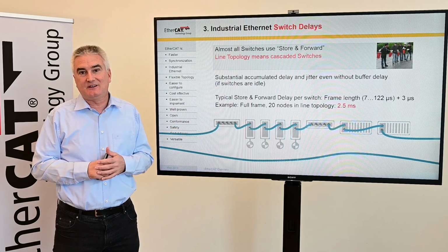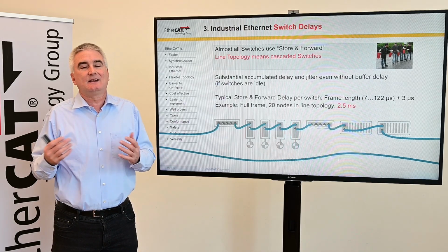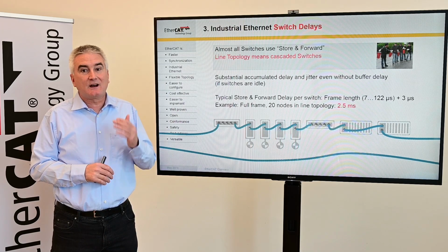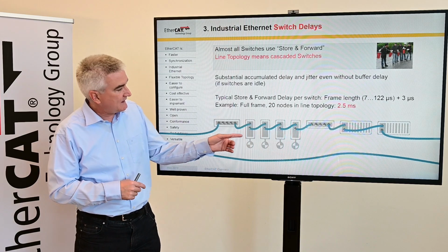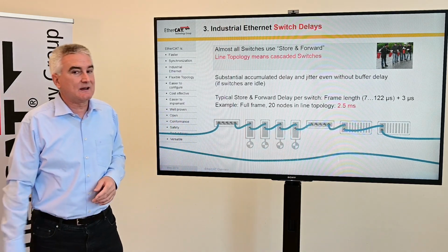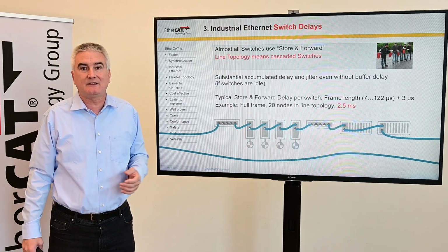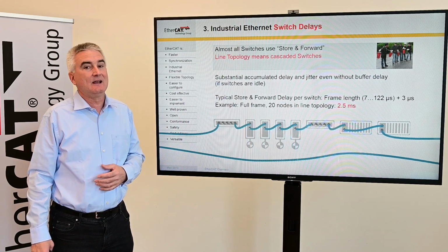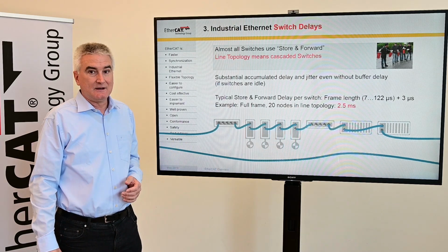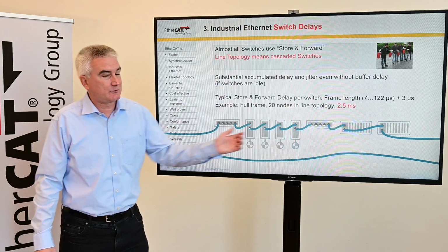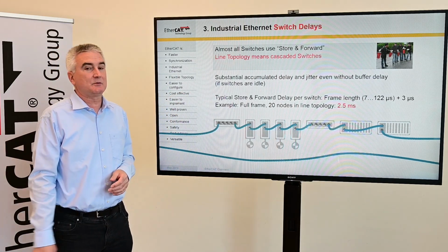That's why we call it the Ethernet fieldbus. We make use of Ethernet technology, but we're as simple as a fieldbus, and we're not considered an IT network by the IT people. By the way, you see these don't look like switches at all, but any two-port device in a switch-based industrial Ethernet technology has a switch chip inside, so it has to be considered a switch, and it also contributes to the cascaded switch issue that is typical for store and forward methodologies.